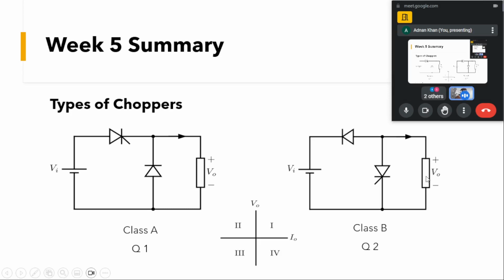So we'll be having a negative voltage that will be charging this inductor, and the current will flow through this device when this device is on, and the direction of the current will also be negative. And when this turns off, the polarity of the inductor will get reversed, this diode will be forward biased, and whatever energy is stored in the inductor will be fed to the source.